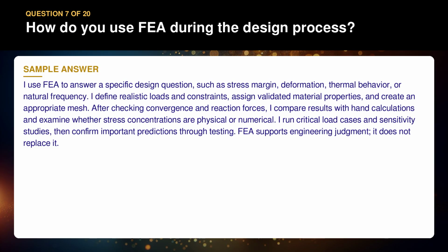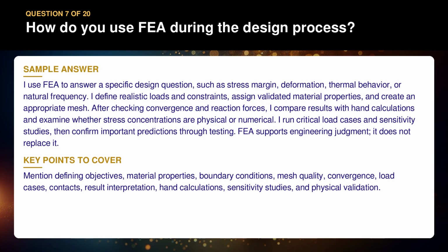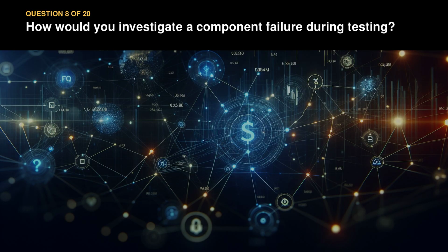I run critical load cases and sensitivity studies, then confirm important predictions through testing. FMEA supports engineering judgment, it does not replace it. Mention defining objectives, material properties, boundary conditions, mesh quality, convergence, load cases, contacts, result interpretation, hand calculations, sensitivity studies, and physical validation.